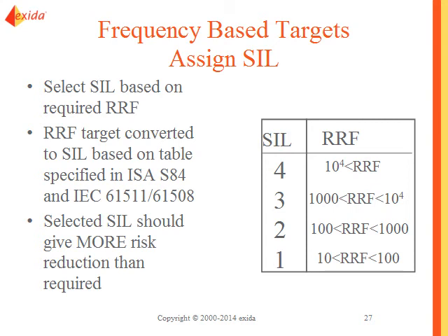And you'll see that as we get into more detail, it's very important that when you are defining the SIL for the SIF, you make sure that there's no chance that the designer, who may not be and shouldn't be the same team, will be able to interpret it other than what you have specified. So again, if you're looking at qualitative, you will get order of magnitude SIL. If you're looking at quantitative, you can be much more accurate, and you can put in a safety margin. And we'll talk about that in a minute.